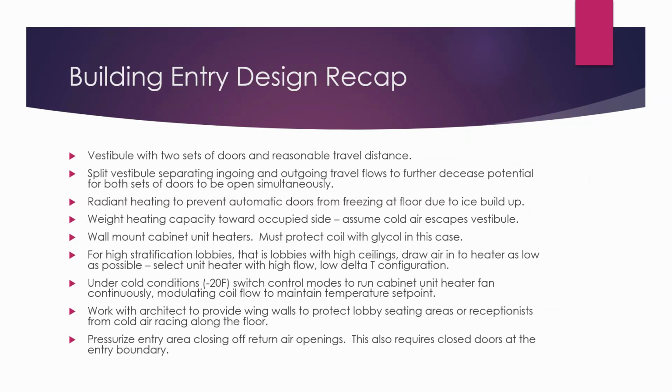So here's a good point. Cabinet unit heaters are often just run off of a single line voltage thermostat, and this is a perfectly fine way to do it.